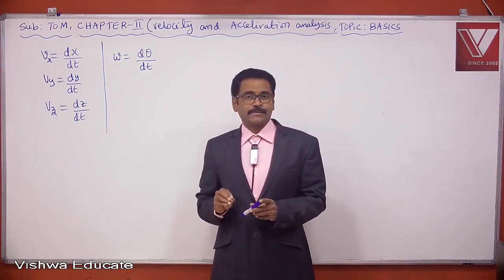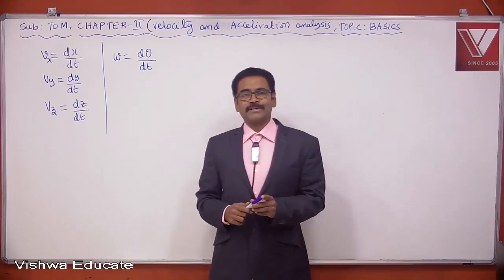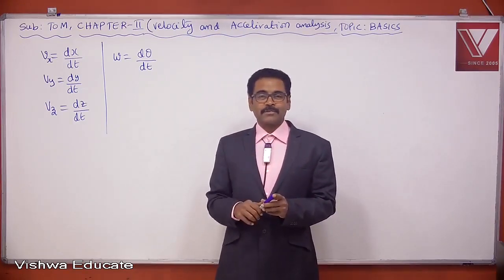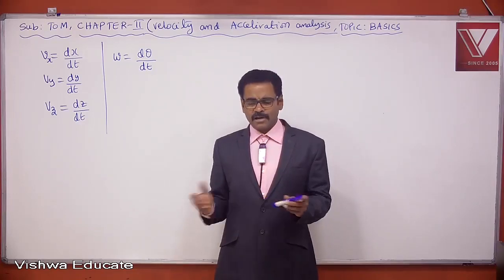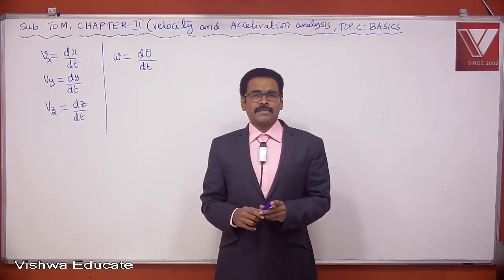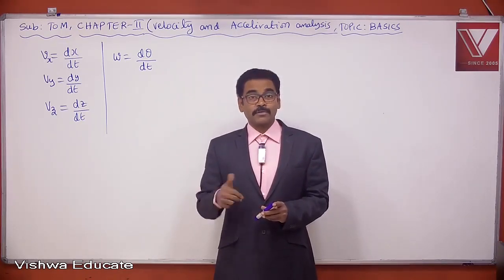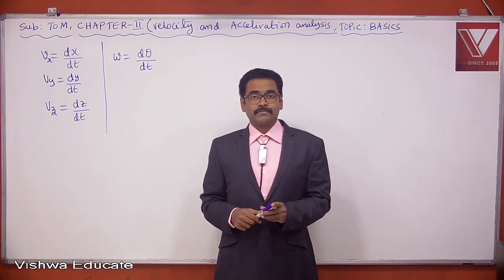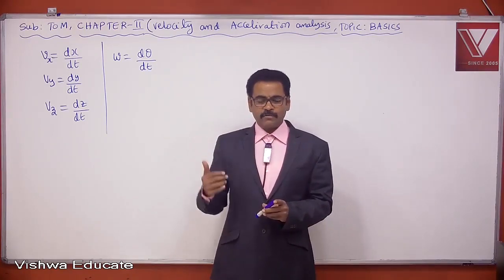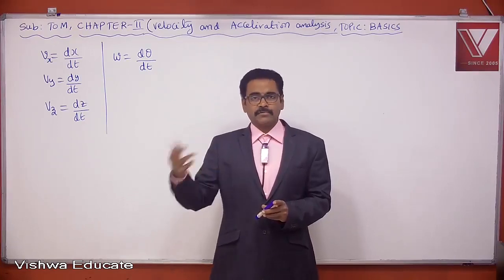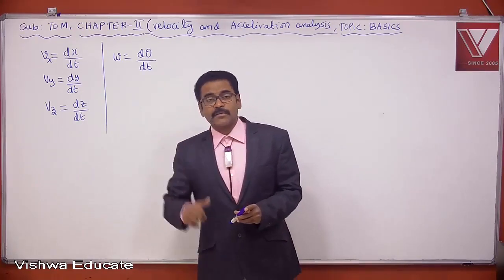Force analysis. What is force analysis? Force analysis means calculation of forces carried by various links of mechanism, or fixing of forces for various links of mechanism is called force analysis. For existing mechanism, it is calculation of forces. For new mechanism, you have to fix what is highest force on a particular link in a cycle of operation.